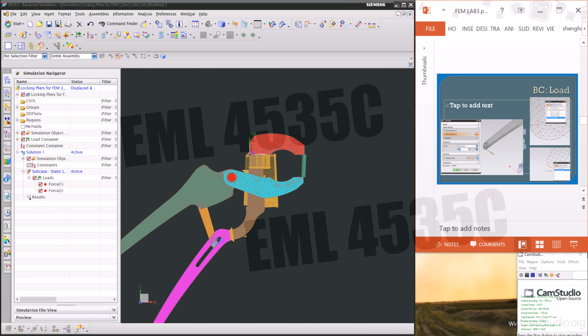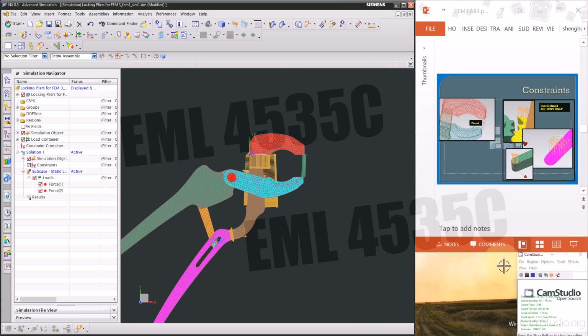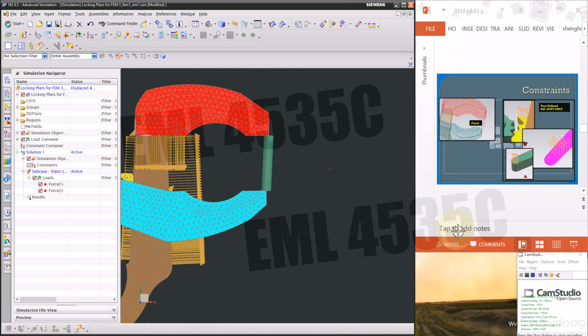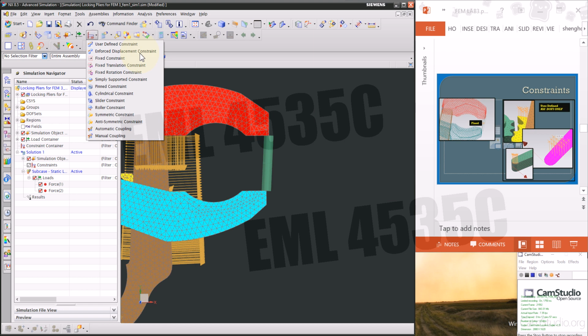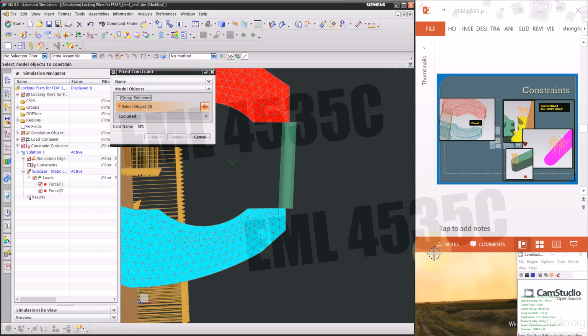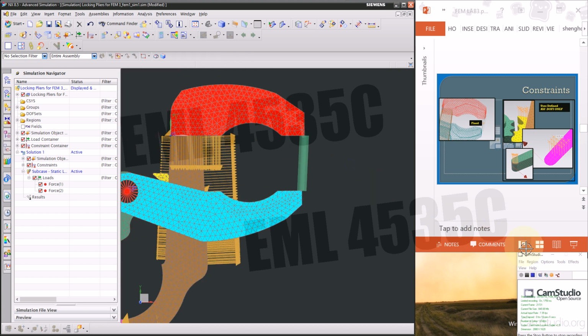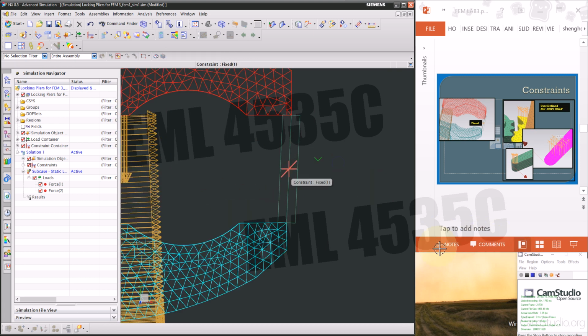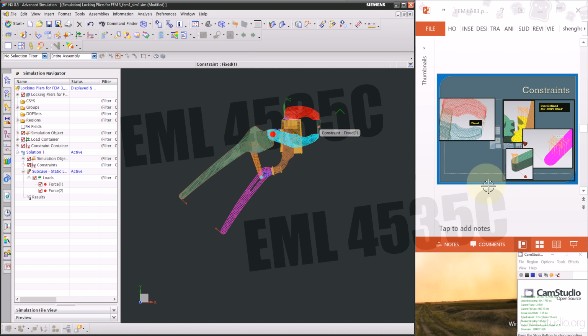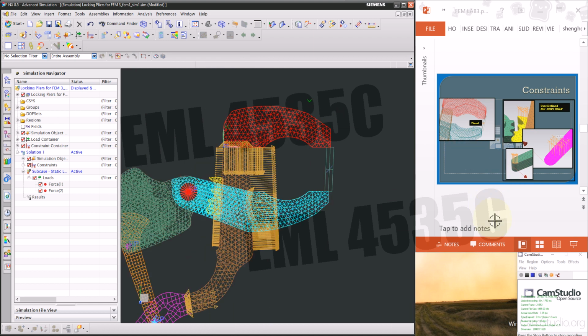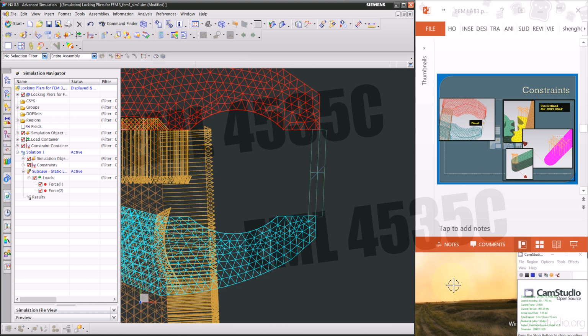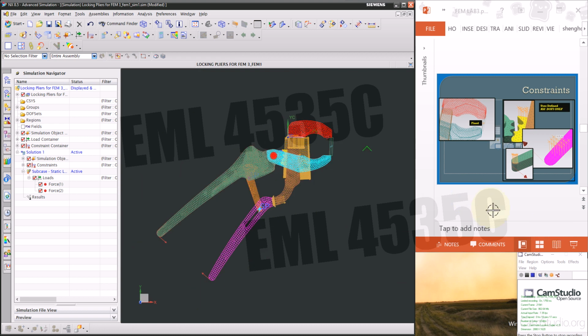For the constraints, we have two types of constraint. The first constraint is easy to visualize: the fixed constraint for the model in the center of this nylon bar. So that one's here. Once you have the fixed constraint and we apply force, you squeeze it, and the two jaws will come together towards the center. And the second constraint will kill degree of freedom 3.